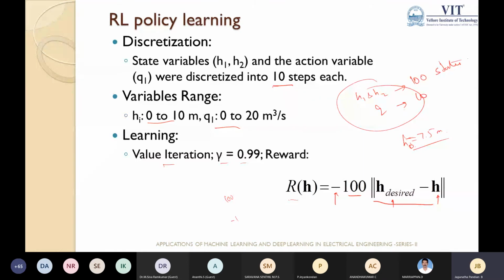You have to say this particular zone you have to avoid, say where you may have your sofas or chairs. That particular state your robot should avoid, so you can create a -100. Whereas with -1, your robot can go through it, it can stay, but it has to leave. 100 is the target, but -100 is the state it should avoid completely. So like that you can plan.